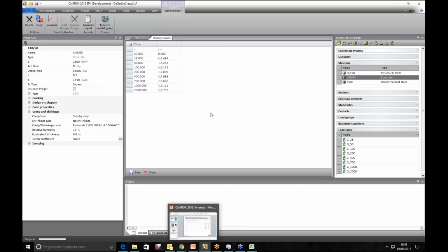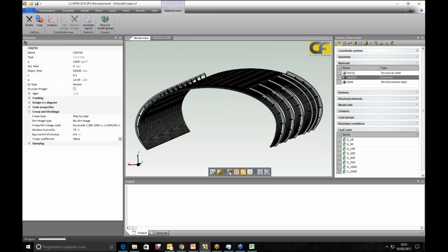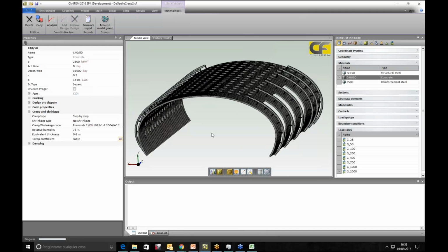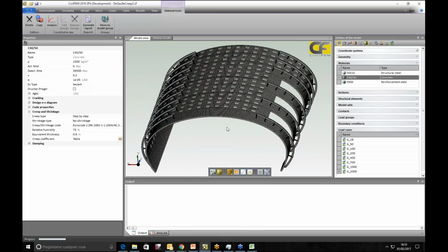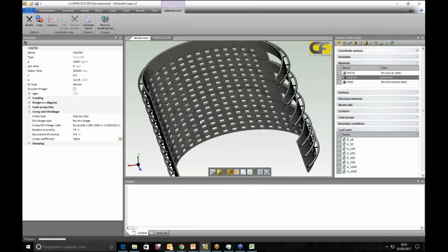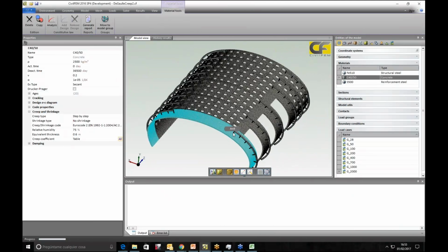deformations. We can also see that this model, taking into account second-order effects, has a very thin slab; the thickness is low. So we will also have deformation problems. We have found three problems: holes, connections, and high deformations. So the next step is trying to model all of them together. The holes are here, and the connection problems should be added to creep.